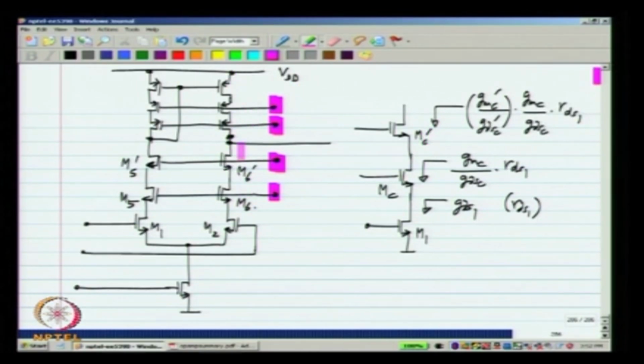Also, an additional constraint is that you have now stacked more transistors. So, that means that things will be constrained even more than before. So, you can have more and more cascodes, but you will have lesser and lesser swings, but when you have a two stage op amp, the swing at the output of the first stage does not have to be very high. So, it is possible to do this. So, sometimes when you want even higher DC gain, you could go for something known as a triple cascode in the first stage and a second stage. So, there are lots of alternatives and lots of possibilities.